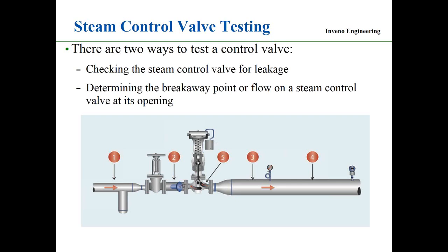Now, if you're just heating water to 80 degrees C, and you can take 5 plus or minus 5 degrees C fluctuation, it's not a problem. But we get in processes where you have to have plus or minus 0.5 degrees C. So this breakaway point inside this control valve becomes very, very important. Okay. So there's a couple things that we do on the control valves, setting up this control valve for the breakaway point and understanding the breakaway point in the valve, and that's setting up the control valve.